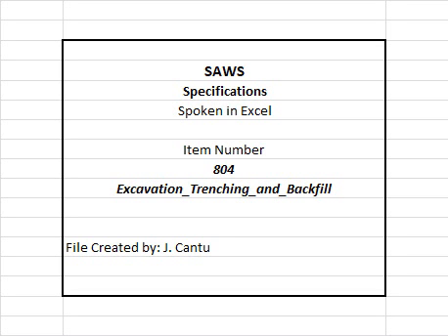K. Bell holes and depressions for joints shall be dug after the trench bottom has been graded and bedding installed. L. The pipe shall rest upon the new bedding material for its full length. M. The minimum allowable base width of the trench shall be not less than 12 inches greater than the exterior diameter of the pipe, not less than 6 inches on each side.